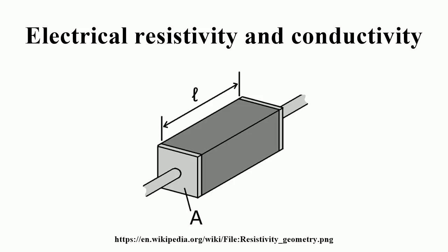The larger the cross-sectional area of the conductor, the more electrons per unit length are available to carry the current. As a result, the resistance is lower in larger cross-section conductors. The number of scattering events encountered by an electron passing through a material is proportional to the length of the conductor. The longer the conductor, therefore, the higher the resistance. Different materials also affect the resistance.